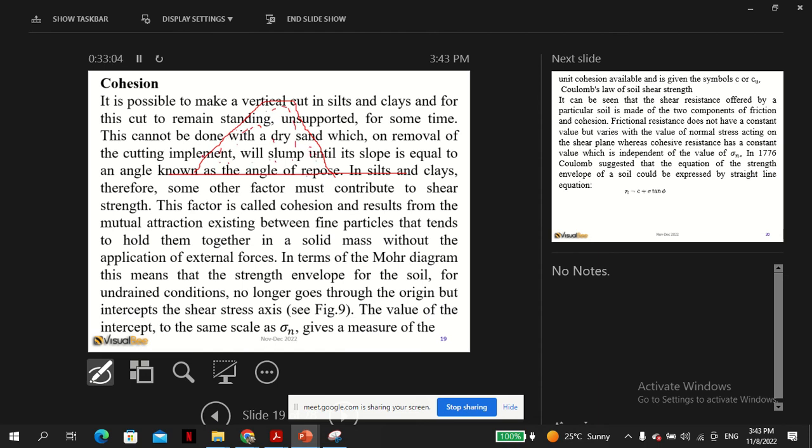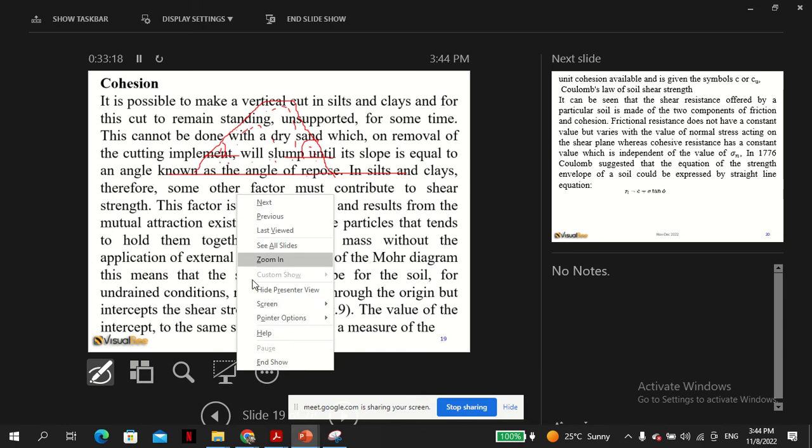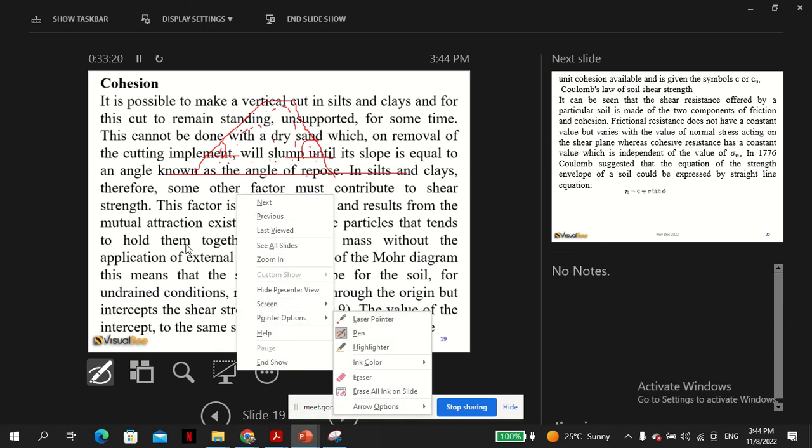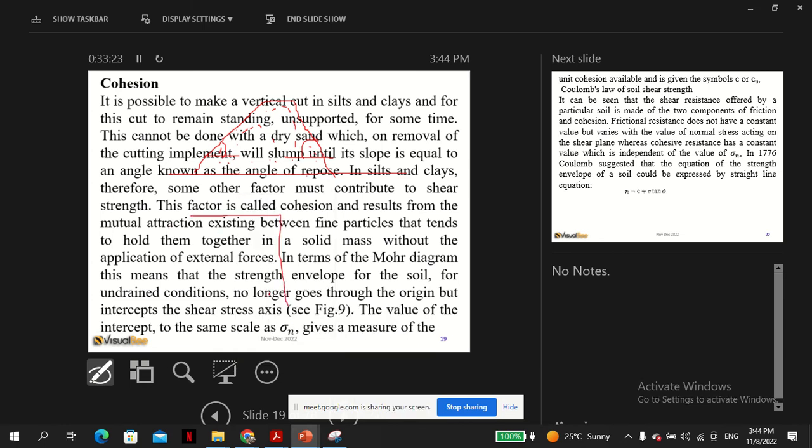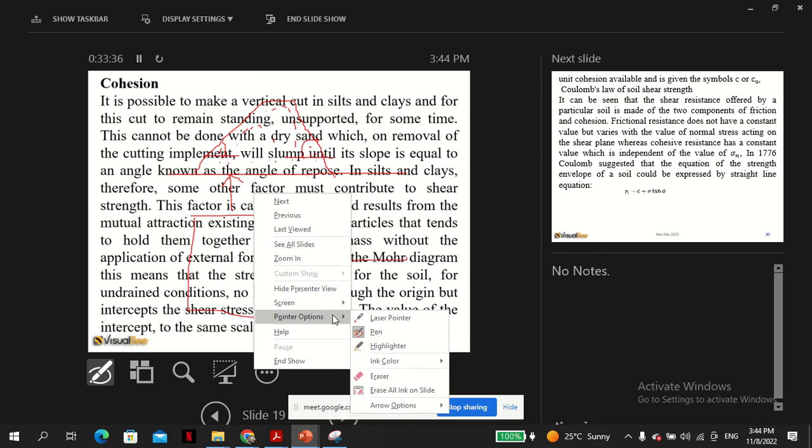This angle is what is called the angle of repose, the angle of free standing. If this is flour or loose soil, that's what you call the angle of repose. If you try to make a sample like that stand on its own, it won't. It will just collapse until it reaches the angle of repose. So this is the idea.